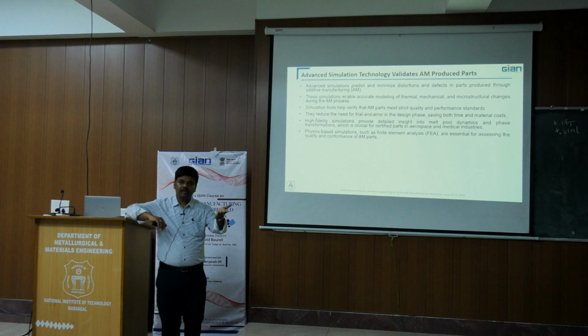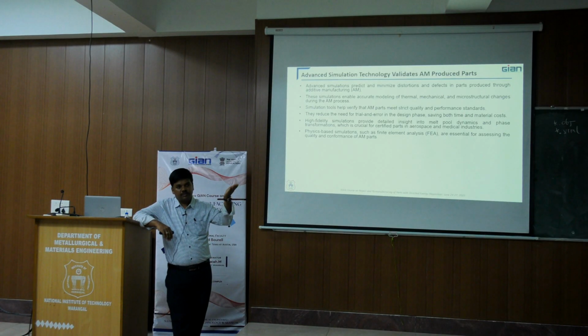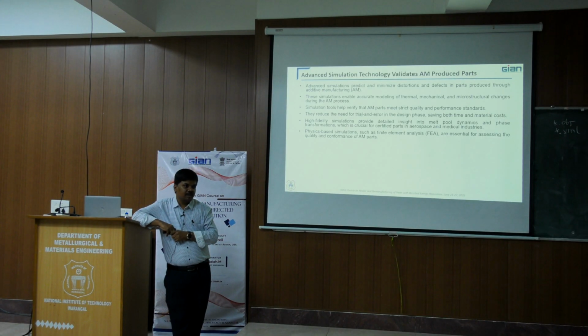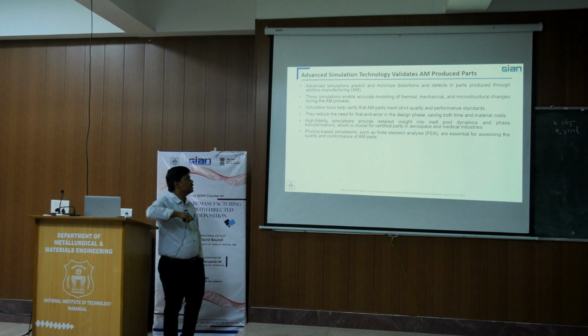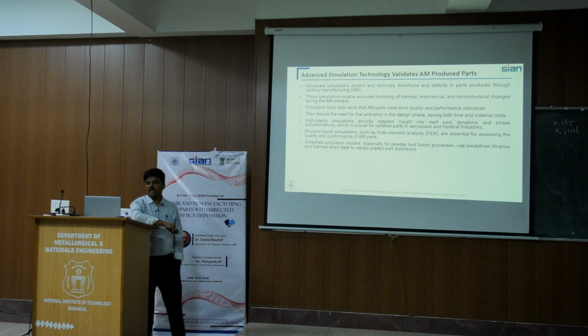Because once the part is developed to several heights, the heat accumulation is also going to be very high. Then we need to optimize the laser power with respect to the scan speed. And if you do not optimize the scan speed and the power, then you will end up with a lot of thermally induced and deformed parts at the end. That's why it is required to understand the physics-based simulation aspects.